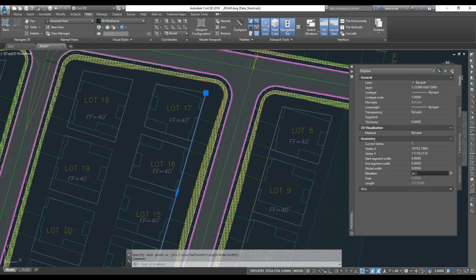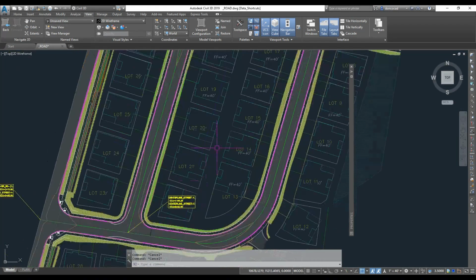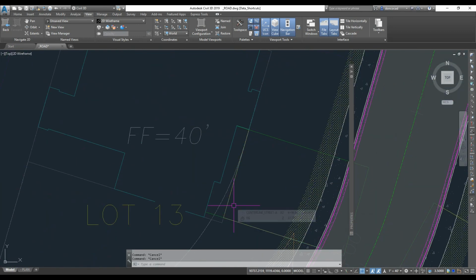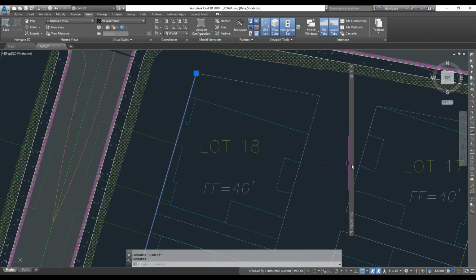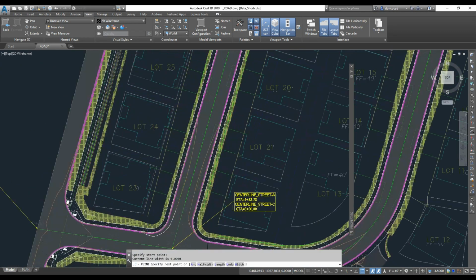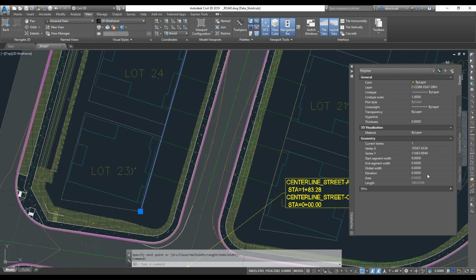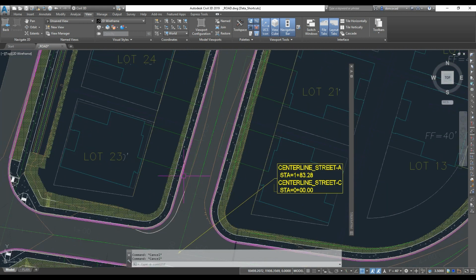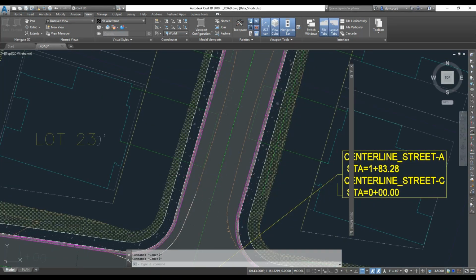And just draw all these, set them at the elevation, and then just go back and trim them. They're all in the same. One thing about it is you can put these in by layers, in which I'm a strong advocate of drawing everything in different layers that make sense. And then you could set that target in the corridor by the layer.